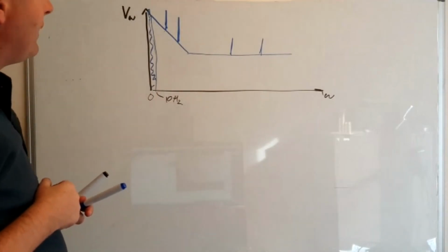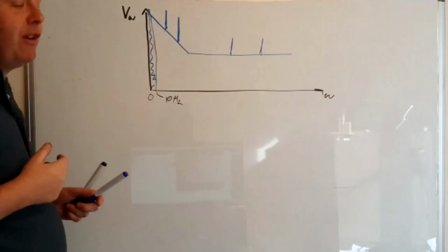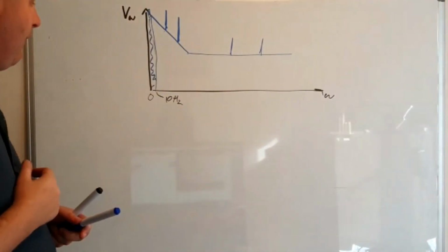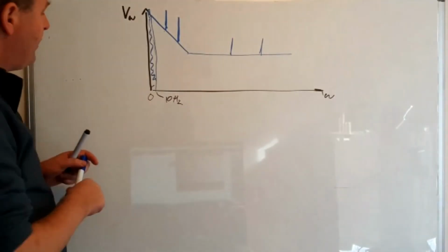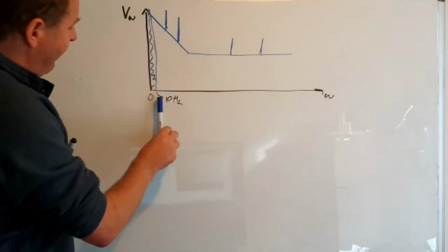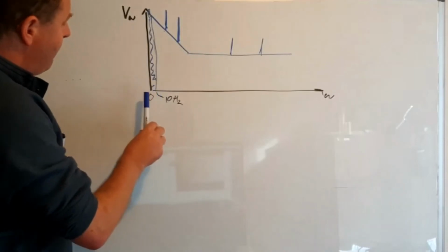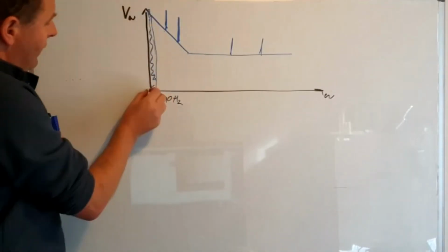And all we can go and do about that is try and average for longer and longer and longer to try and beat that noise down. If we're doing averaging for longer and longer and longer, what we're doing is we're effectively moving this bandwidth to smaller and smaller numbers. So rather than being a strip this wide, we look at a strip which is much, much smaller.